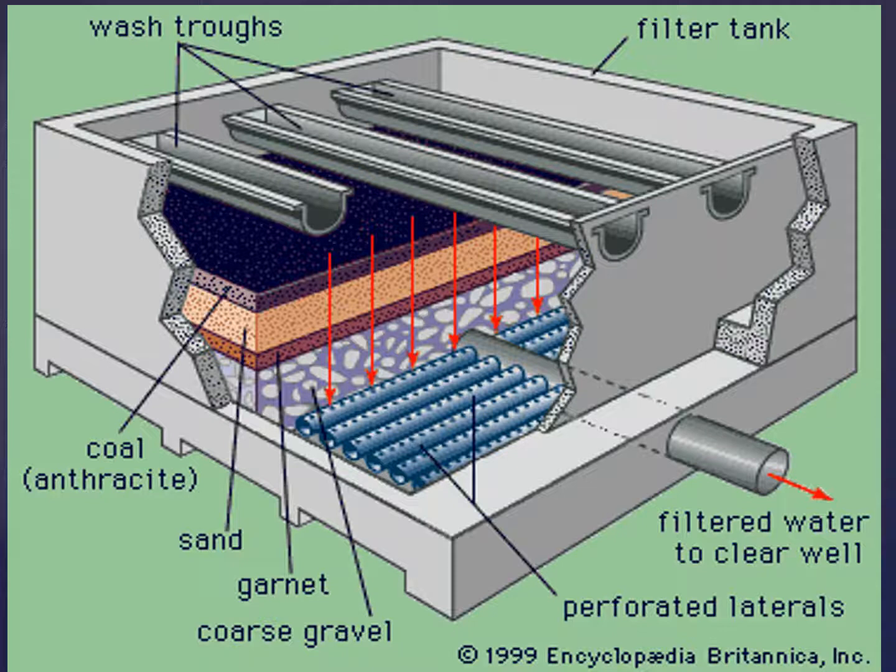Again, here there's another picture at the top and left, that is a wash trough. So you collect water from the top, that is for backwashing, that is for cleaning, that is not during the filtration. So when you filter, you stop filtration, you backwash it.